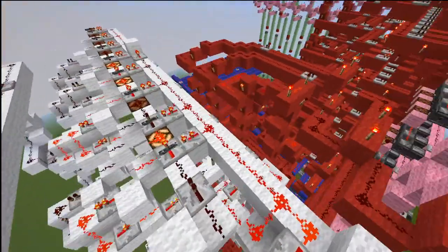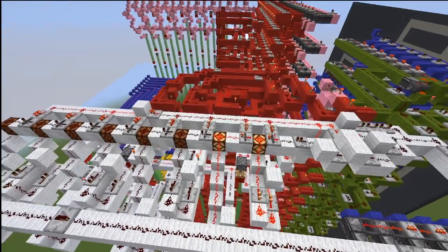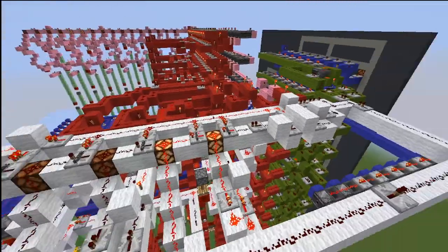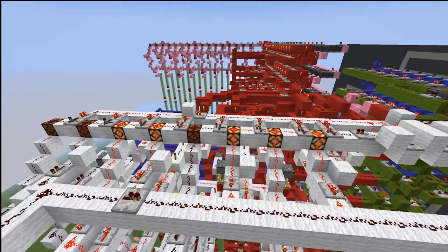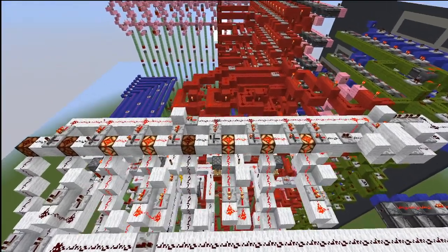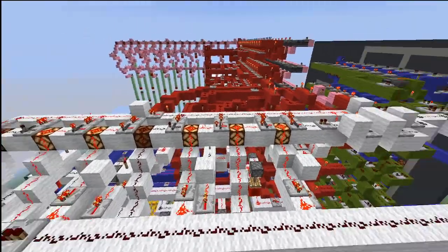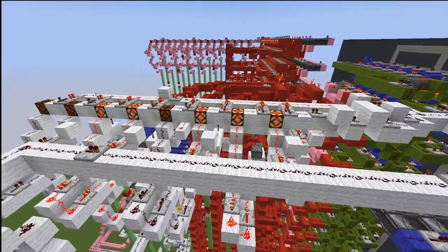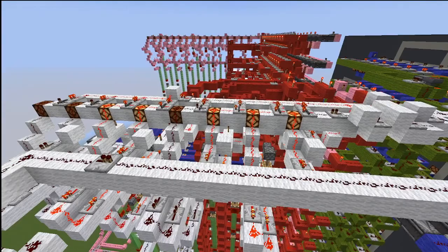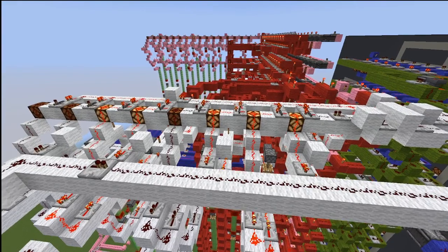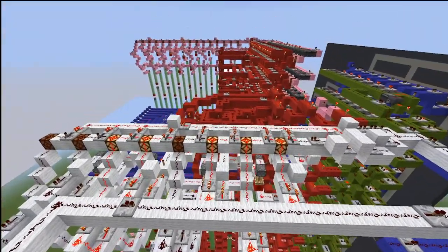So we're going to see the program counter read what's in the program counter, and it's going to give that 3, like I said, and then it's going to select 3 from the prom line. And sure enough, that was what was in prom line 3. So it's going to take what's in prom line 7 and update that to this data bus here. And then it's going to send that to the B register, and since it's already by default in subtraction mode, it's just going to send that result to the A register.